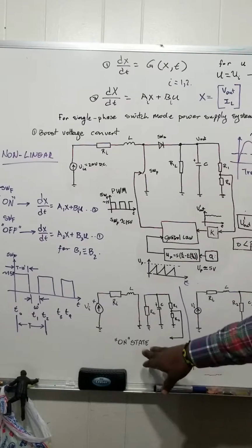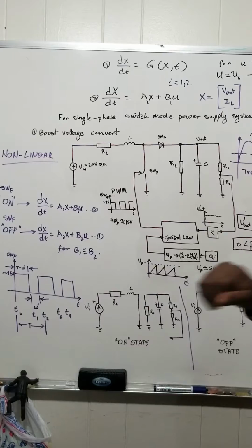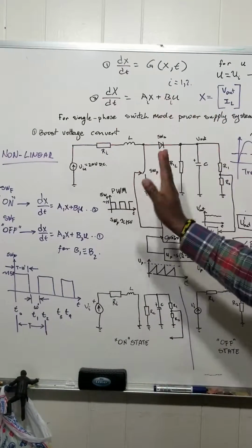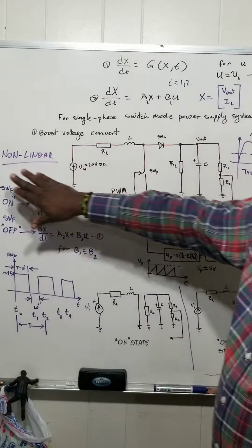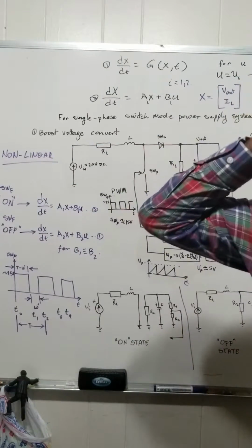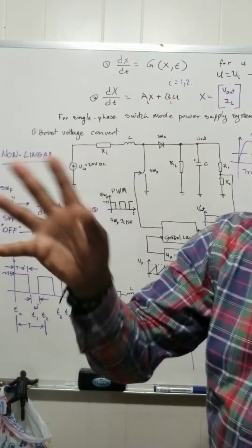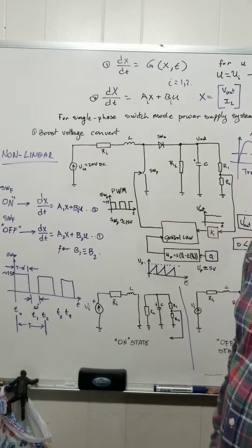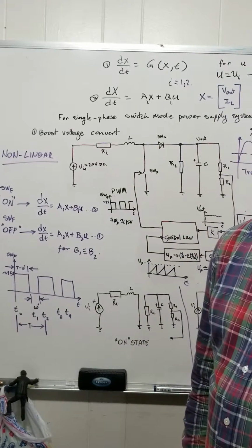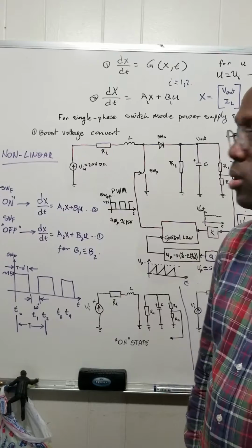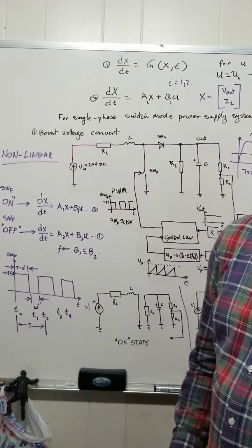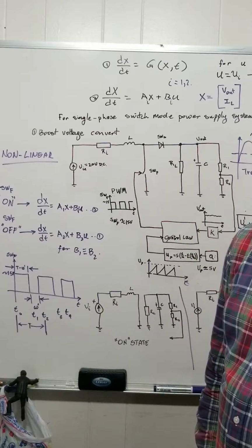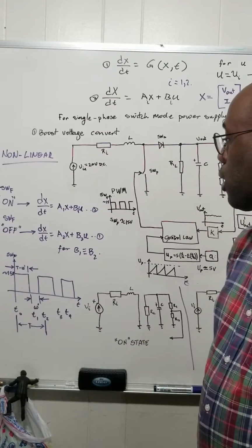Throughout that, we'll work it on the two stages. So for now, I won't be looking at the discontinuous mode. Normally, it's mostly worked with the buck converter. So when we start with the buck, we look at the various stages of the buck. The buck is used in basically all electronic devices that we have. A lot of electronic devices use a buck converter. This one is mostly used for solar systems, battery chargers, etc.